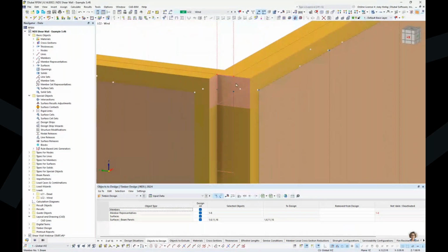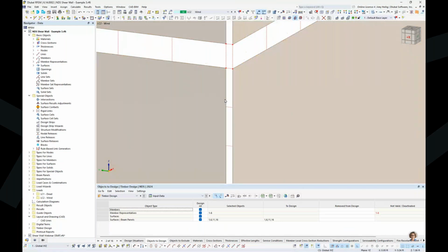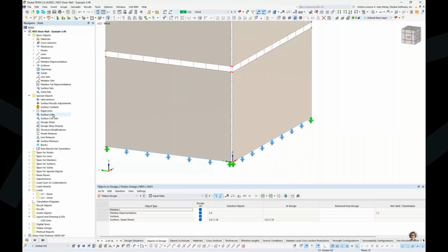This is almost like a BIM approach to the modeling here. The reason why is because if we had interior sheathing, we would see that overlapping if we fully connected the two panels at a single line element, which could cause issues in the program. Now, we want to continue improving on this topic, but until then, again, you can model a simple gap here and connect those with your own rigid link.